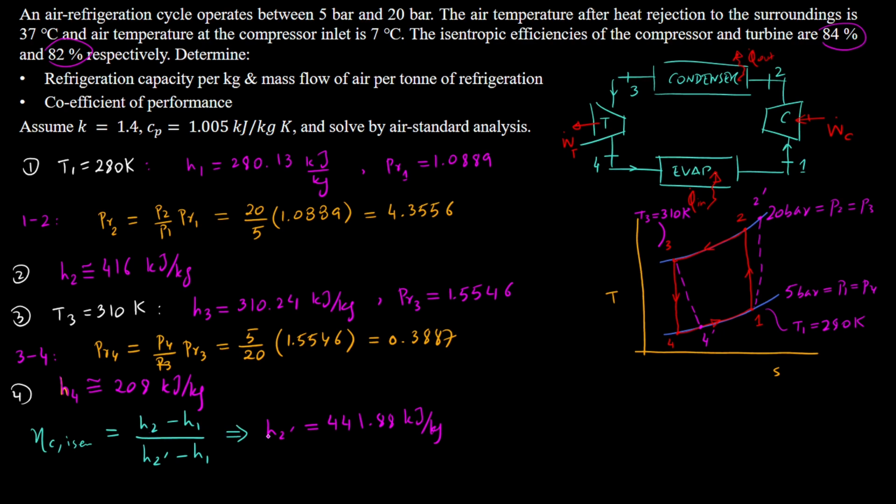If you work it out and you find that H2-, once you found it, is smaller than H2, then you're going to be wrong. So H2- is most probably going to be larger than H2, right? Over here it's going to be up higher, and enthalpy is usually increasing as we go up the TS diagram, as we go up vertically, so it should be increasing. So H2- should be a higher value as compared to H2.